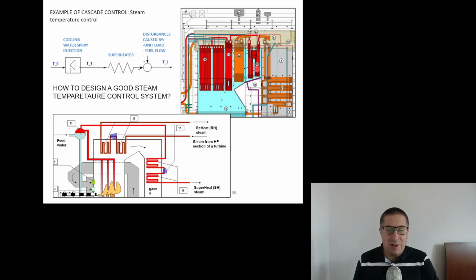If we have a boiler with a drum, a typical 200 megawatt unit, it would be 540 centigrade, right? And a high pressure. Once again, depending on the type of the boiler, 15 megapascals, 20 to up to 25 megapascals.